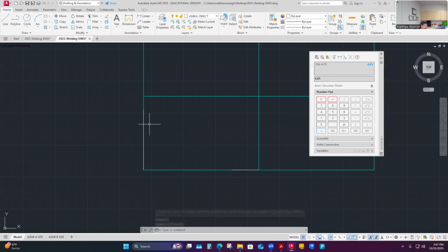I could have drawn that on the construction layer, and then I would have this endpoint to hook these two up. But I'm just going to do what I call a cursor command. I'm going to delete this real quick. I just deleted that. I'm going to call what I do a cursor move. I come up here in the command and target a point that I want to base my movement from. I don't click anything and I just start moving in the direction that I want to go.